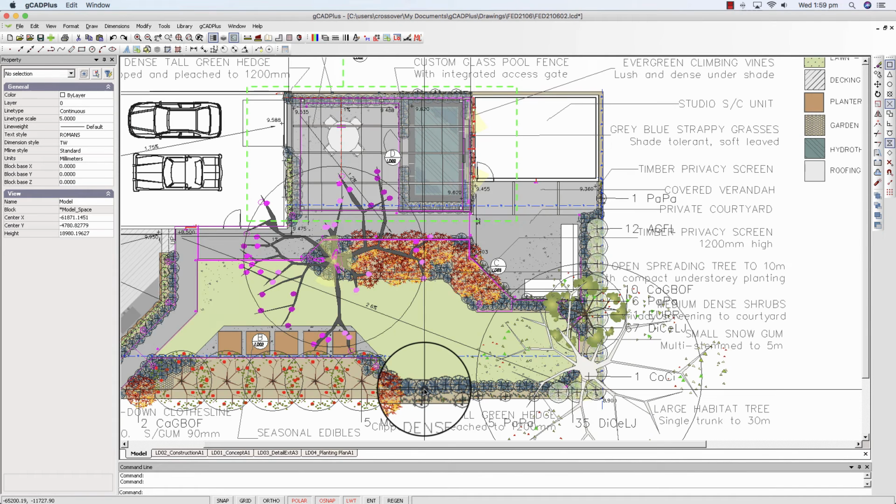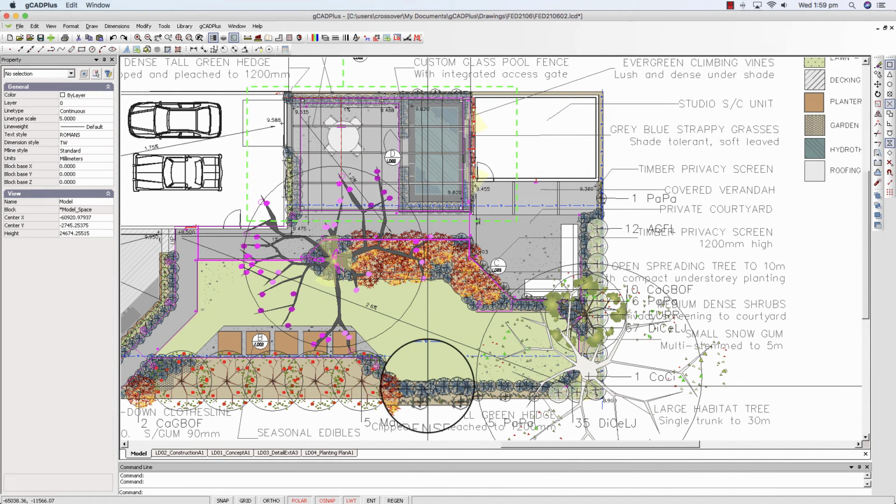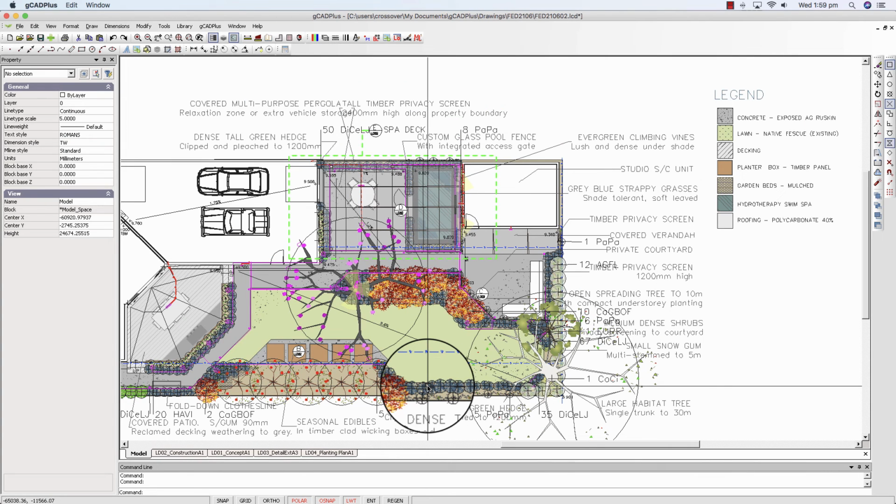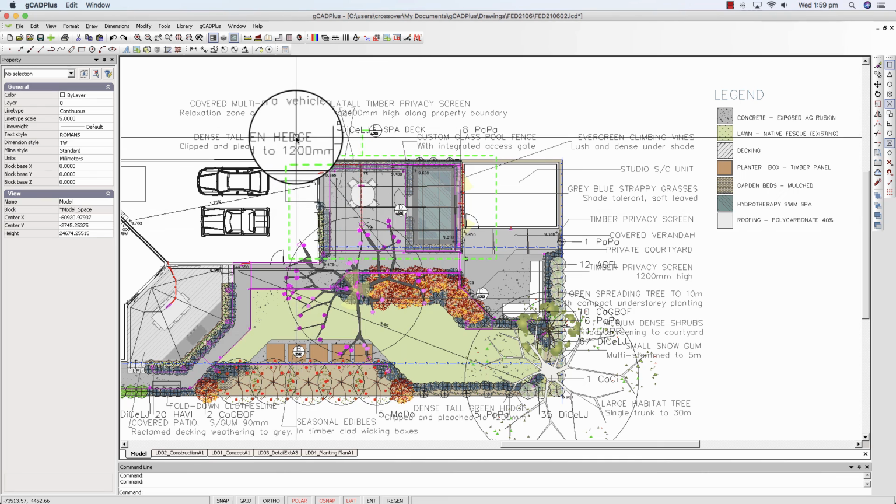so there's a few tricks here. You have to create a layer state, give it a name and set the on-off switches for that particular layer state, and then you have to remember when you're swinging from one to the other to recall. So that's a particularly powerful tool and a quick way to work.